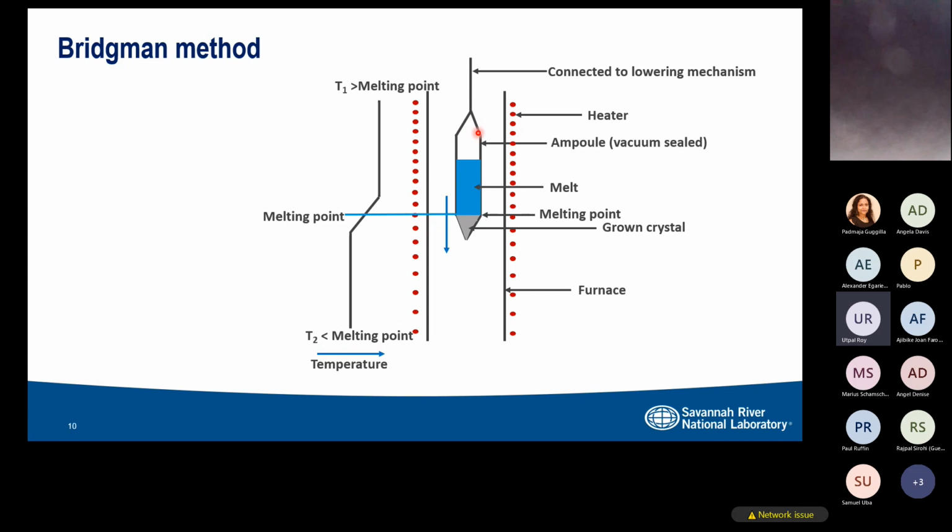So if we put some cadmium here, that itself will build up enough pressure so that it will resist vaporizing the cadmium from the melt. So this is one technique. Another technique is that we can basically encapsulate, or we can put some material so that it floats on the top of the melt without reacting to the melt.